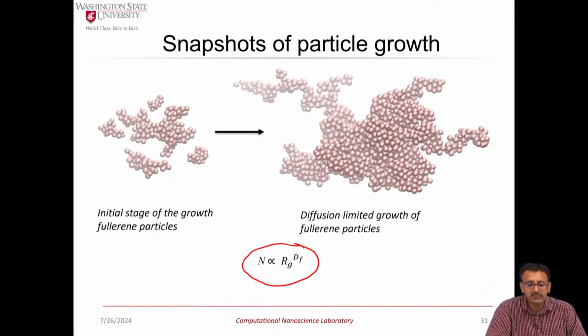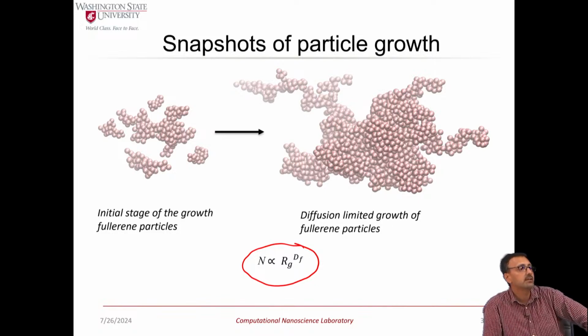I'm interested in extending this to other processes, like I mentioned, perhaps sintering. But then there is an additional situation: this is a system of spheres, which you can call either hard spheres or soft spheres. At the MD level, it's a soft sphere. But if you have sintering, obviously one of the key things is that, due to the thermal energy, there will be diffusion and deformation of these particles, which is certainly not considered here, and which you would have to consider for a sintering process.